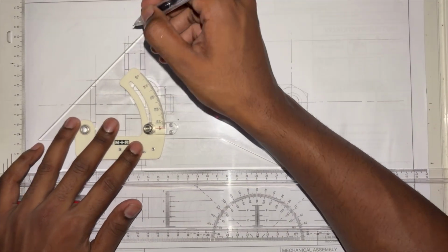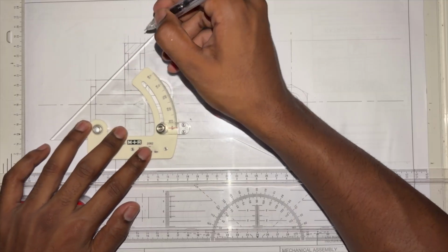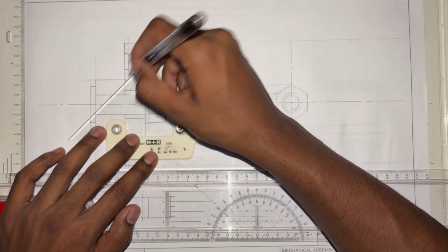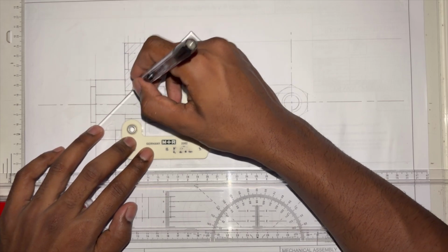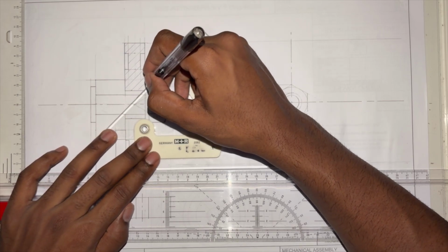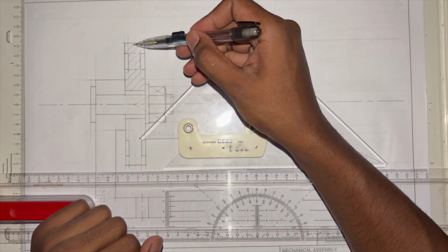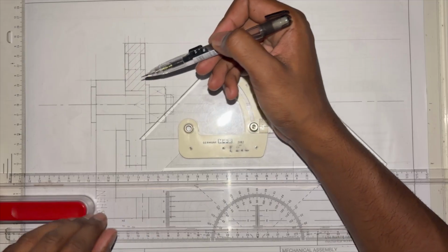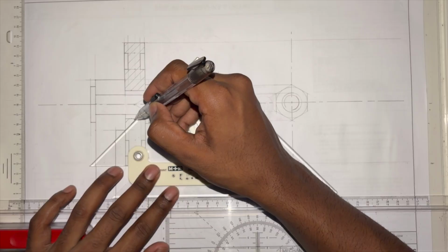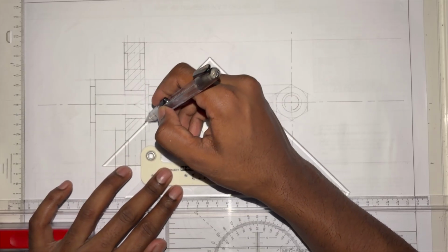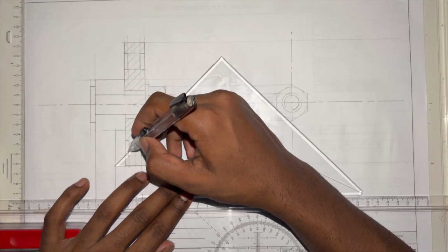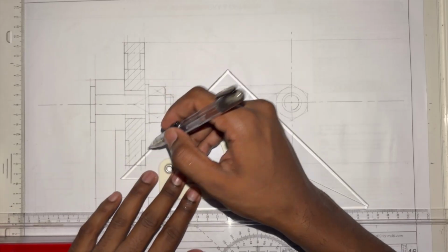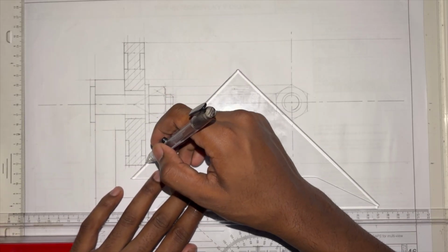Okay, hatching. Now, every component needs to be hatched differently. If it's a different piece of material, okay, all these are metal firstly. So metal hatching is line space, line space, line space. It's different from silver hatching. This is metal hatching. Now the pulley is one part, so we're going to hatch the pulley the same. And when I say the same, I mean the same kind of hatching, because it's one part here within this mechanical casting. See, I nearly said assembly.